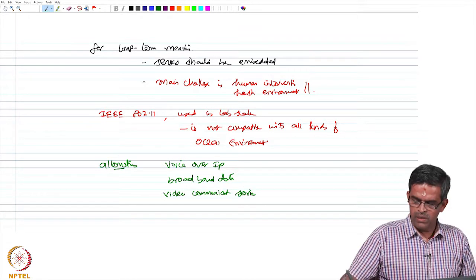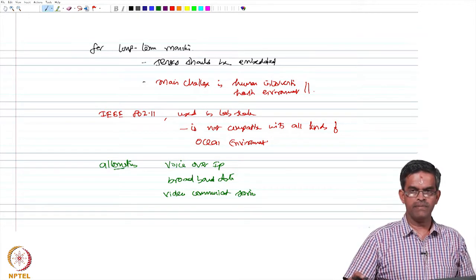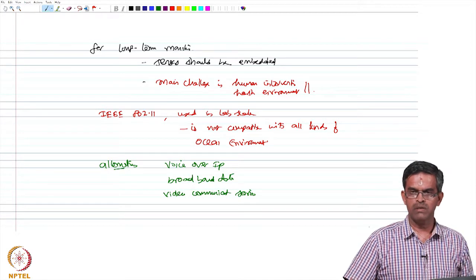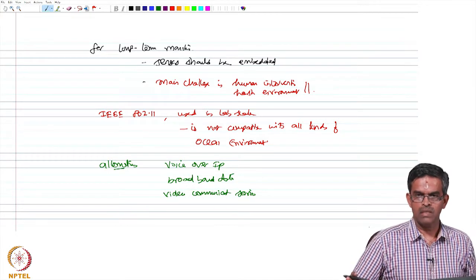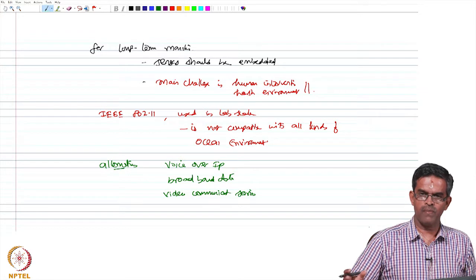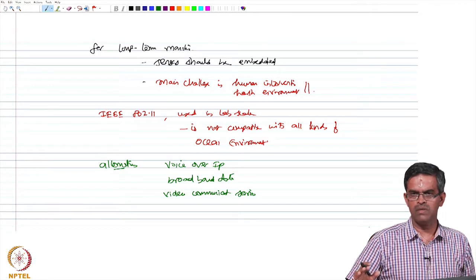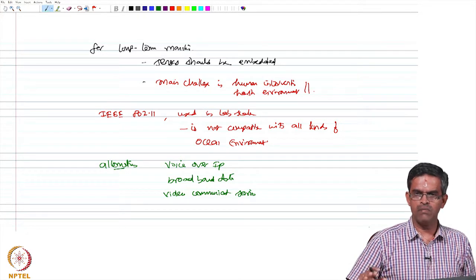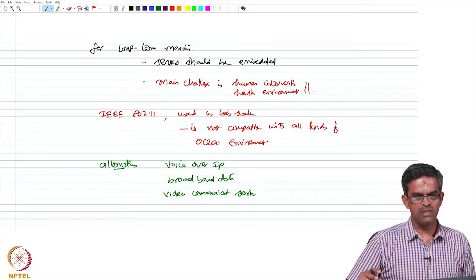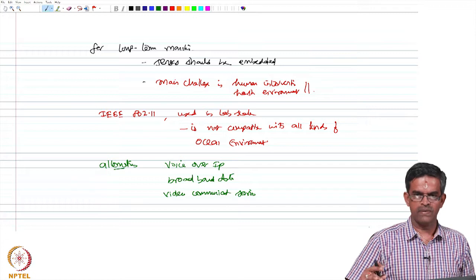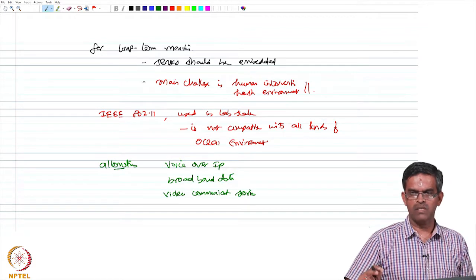So, friends, in this lecture we discussed about the design of structural health monitoring on a lab scale applied onto a new generation platform and showed you each element of the SHM design, compared them with the wired design and showed the advantageous features of different elements: sensing unit, data acquisition, processing unit, communication channels, and alert monitoring systems.